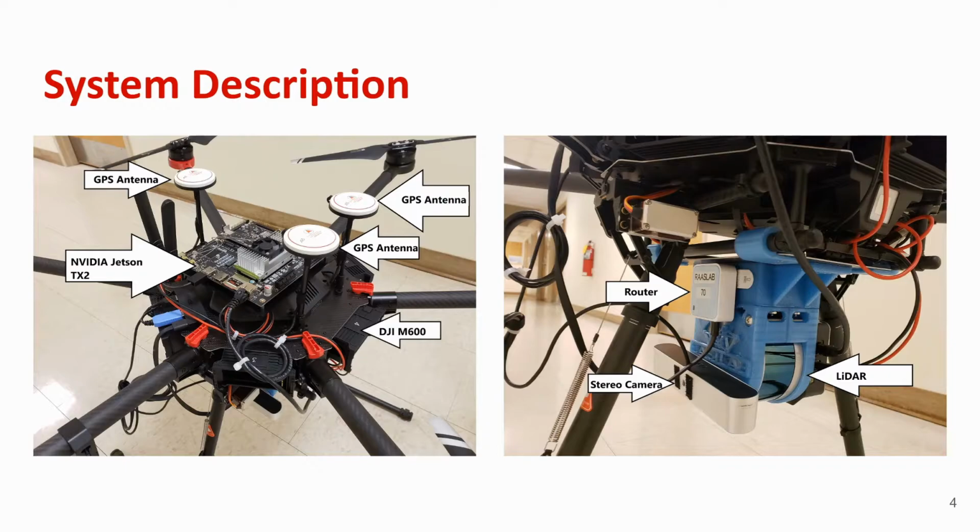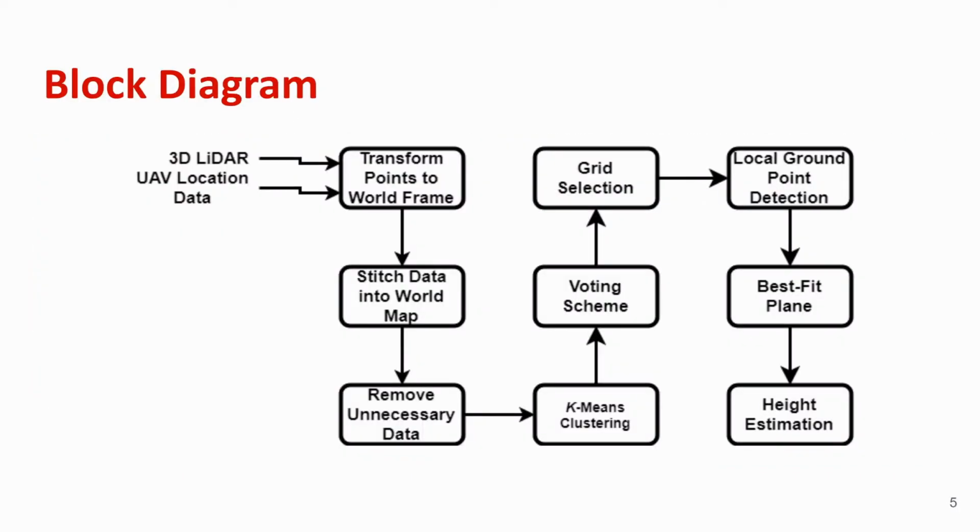Our onboard computer was an NVIDIA Jetson TX2. We also mounted a Velodyne VLP-16 3D LiDAR. The algorithm can be broken down into multiple stages. We take the 3D LiDAR scans and drone location as input and then transform them to a world frame. Then we stitch together a world map.